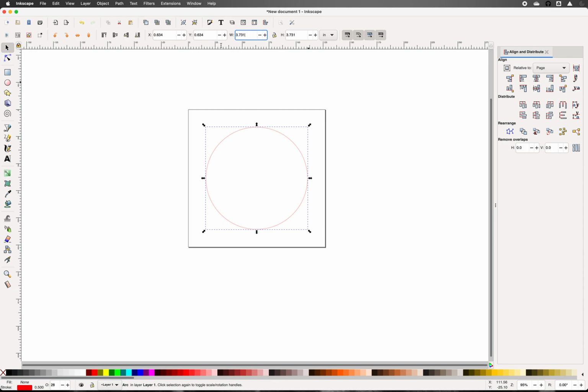So we'll change that to a 4x4, or since it's a circle, just a 4-inch circle, but you have to specify height and width. And now again, we have to make sure we're aligned because we've changed the size of it. There we go. So now we're centered. So we've got our circle where we want it, and we're ready to put text on that.